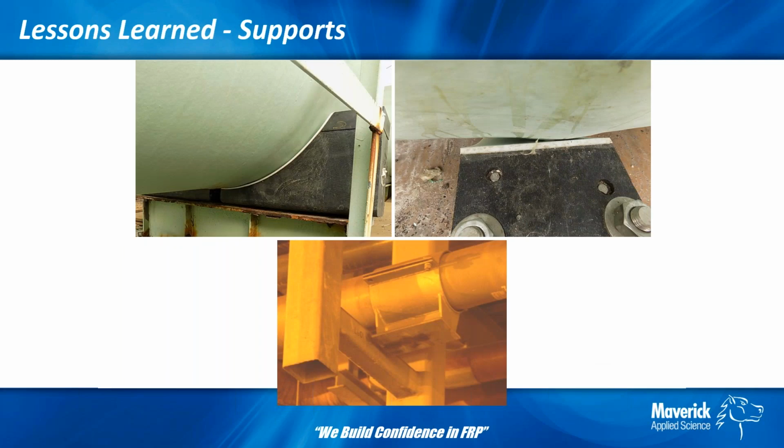So, some more discussion about FRP supports. You can see the pictures at the top here. This is a large diameter duct. And you can see on the right-hand picture where the pipe joint is actually sitting in the supports. You can see the overwrap is sitting in the support, so it's obviously not going to fit well. At this point, the support is creating a point load on the pipe because it's not really got the full surface contact.